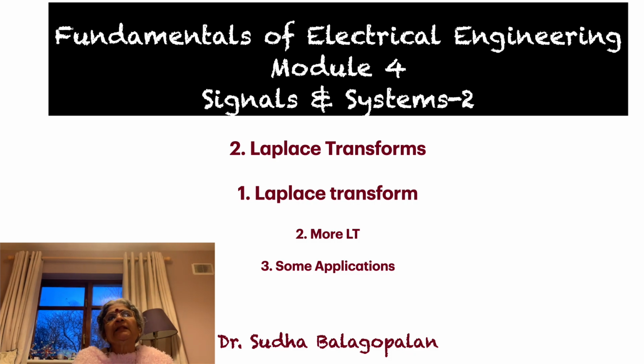And it's very interesting to see that you can take the Laplace transform based on a very interesting understanding, just like the convolution, wherein a signal can be trapped inside e raised to minus st, where s is both the attenuation component as sigma, and then the oscillatory component with omega entered within. And then we also have the window going from minus infinity to plus infinity if it is two-sided. Otherwise it's zero minus to infinity, such that it becomes one-sided. And so we have the unilateral Laplace transform emerging out of it.